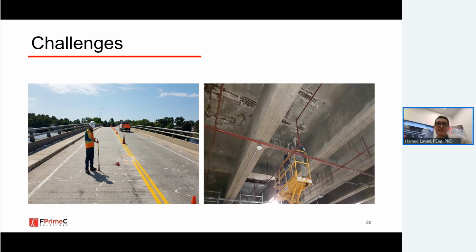Bridge structures, very similar. Now with these wide structural systems where we see localized corrosion, the biggest question is, has this cancer of concrete spread to other locations or not? So this is where tests such as half cell become very useful. They can guide you on how and where to invest your repair and maintenance dollars.